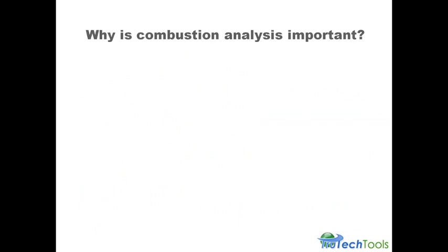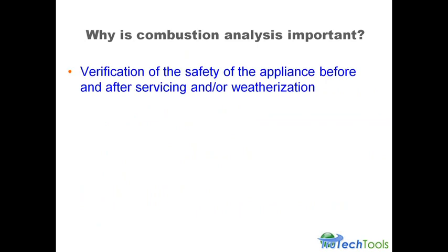Now we're going to start off with really why is combustion analysis important. A lot of people miss probably the most important thing, which is verification of safety of the appliance before we service it and after we service it. We really want to know when we walk in the door, is there a problem? And when we left, did we create one? So we want to check the appliance, test in, test out. And also we want to test it before we weatherize a home, and then test it after the weatherization work is done.